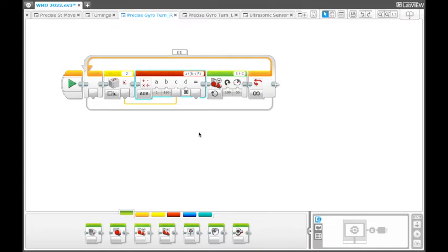If I give 1, it is exactly like B minus C. So if it is giving you some error, then you can reduce the power of the robot. I can multiply this with 0.7, so it will reduce the turning power parameter for the robot, and you will get less error. So this is how you can control the speed using B minus C into D.